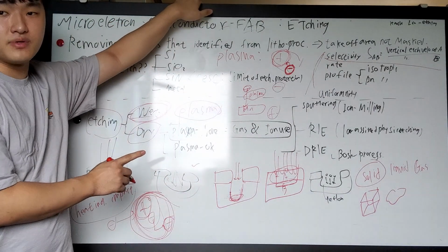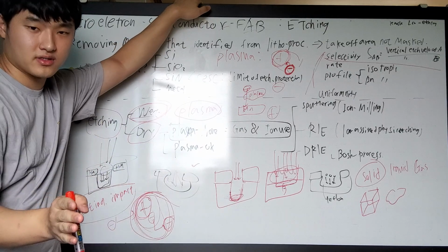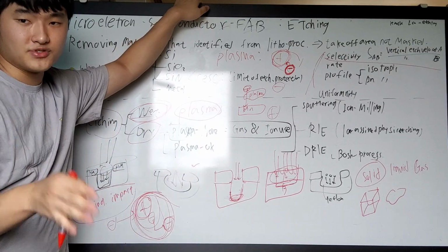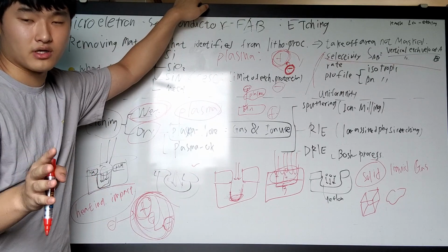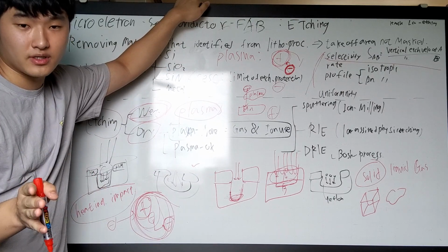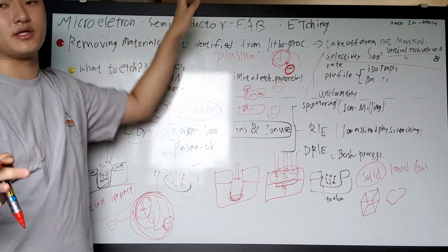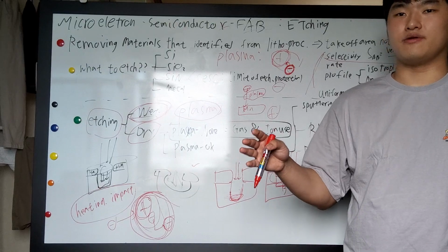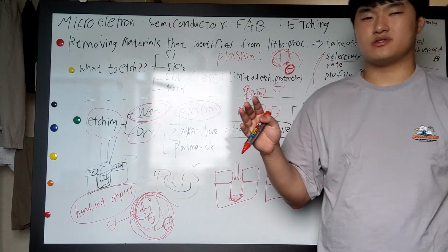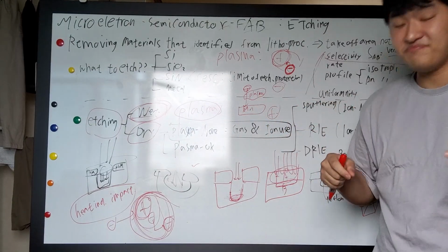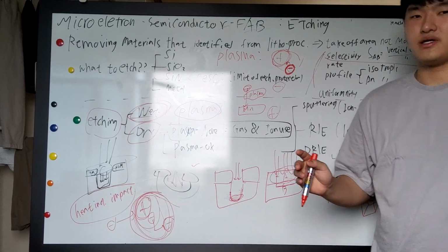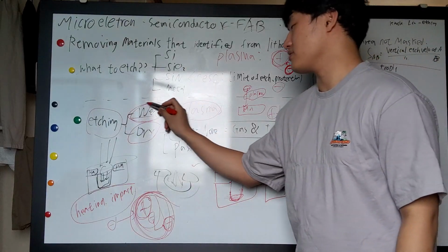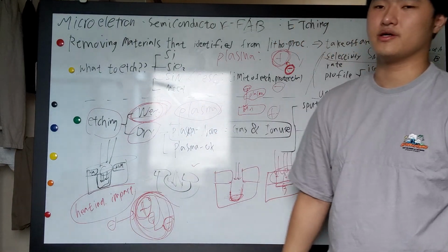So they are very cheap, but as you can expect, the results will not go as you want. It means poor productivity and hard control. But surely it is very cheap. And if you're using a very big wafer, and the wiring is not very small, and your process is somewhat big in diameters, then wet etching can be an appropriate way.